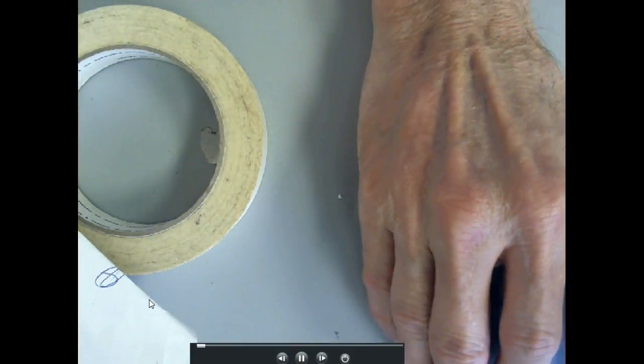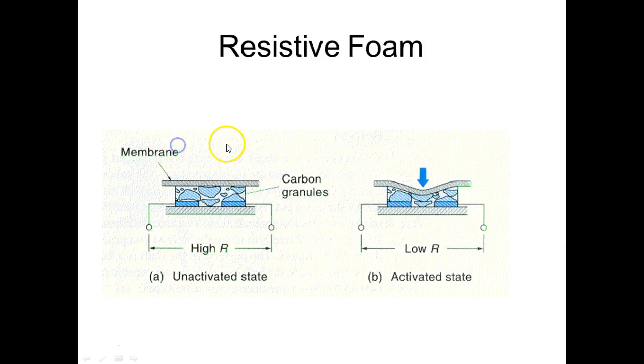This was the popular way, you know, when I was a kid, when you walked into a door, the door didn't open itself up for you. Then they came up with these guys and they'd put these mats out in front of the door, and some old stores still have it. And you have to step on it. Once you step on it, you open the door. We still use them in robotics. We call them pressure mats, where we lay these mats out all around the robot. And when somebody comes up there and steps on it, they generate a force, and then the robot would stop. So these are still used a lot in work cells where the robot cannot be enclosed.